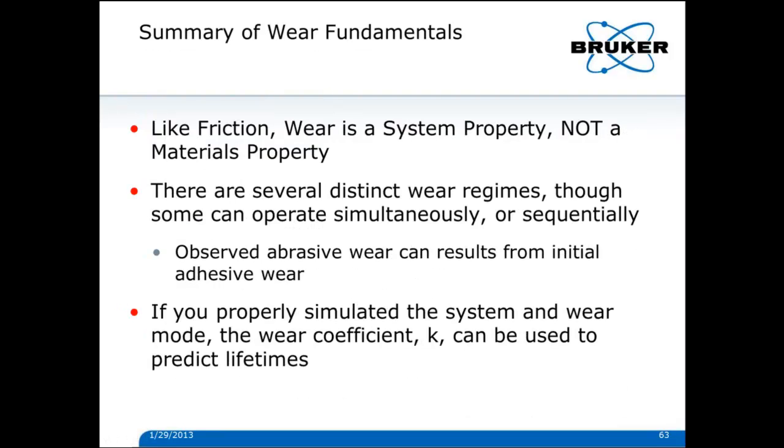If I could summarize the wear fundamentals, like friction, wear is a system property, not a materials property. You can look up wear rates for very well-characterized systems, but in other cases, you really need to measure it in order to apply it to your system if it's not as well-characterized as one you might find in the literature.